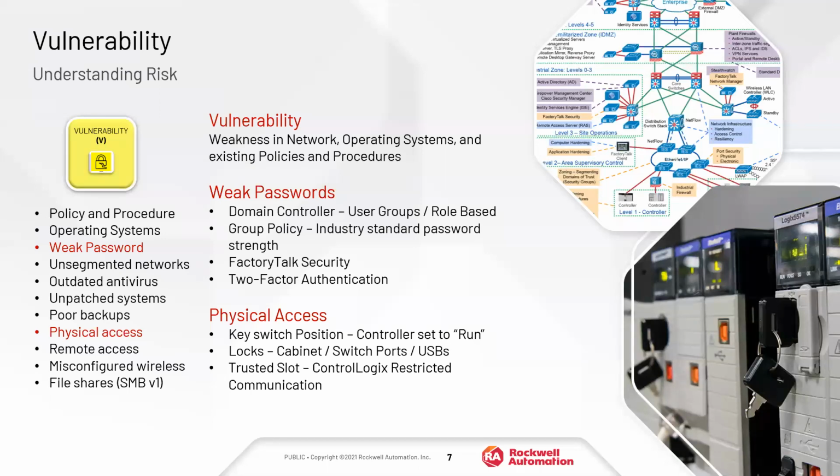One of the biggest uphill challenges in industrial security is actually following industrial security standards in the process control infrastructure. So one big example, and the first one that we're going to be talking about, is weak passwords. I think at this point, we all know someone. Occasionally, we were that someone. We've seen passwords that are written on a Post-it note tied to the monitors. We've all kind of dealt with the operator username and password, or operator 1, operator 2, operator 3.